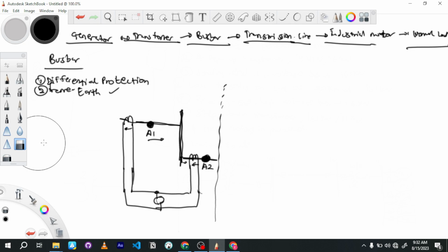For transmission line, you use a few different ones. The primary protection for a transmission line is your distance relay. Now, for distance relay, let's say we have bus A to bus B, and then we have our relay here. We assume all the relays are forward looking. And then maybe you have to assume that your relay is a numerical or digital relay, or electromechanical/static.